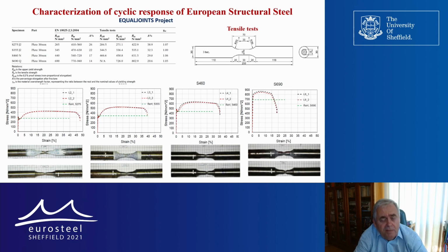So in such a case, even those overstrength members, which could be realized by high strength steels, must be able to develop some plastic deformation.